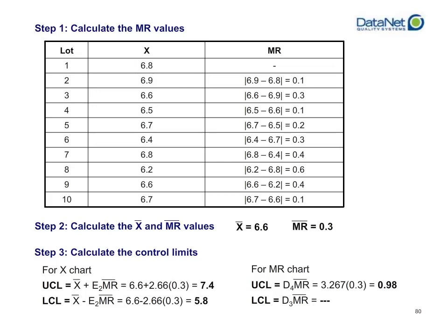Step 2 is again to calculate your averages, but in this case, you're going to be calculating an Xbar, meaning the average of all of your individual samples. And you're also going to want to calculate your MR average, or MR bar, which is the average of all of your moving ranges. This is very important and a point that a lot of people get stuck on. The first subgroup of an X and MR chart has, by definition, no moving range. There is no point for you to be able to calculate a moving range. There is no previous value.